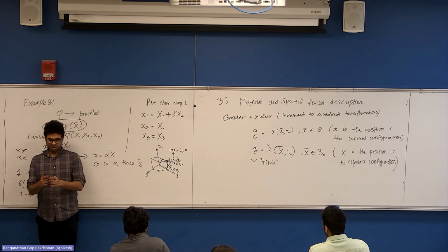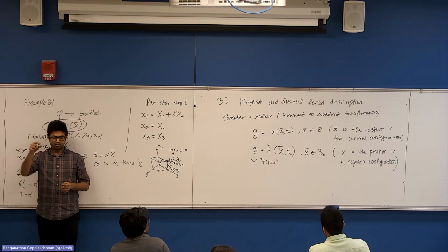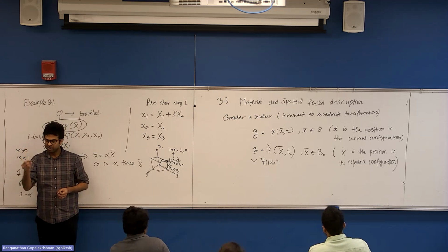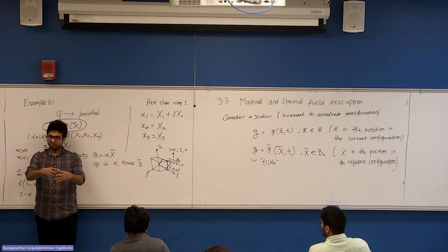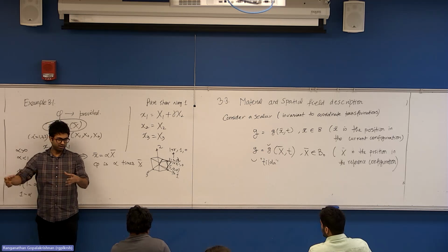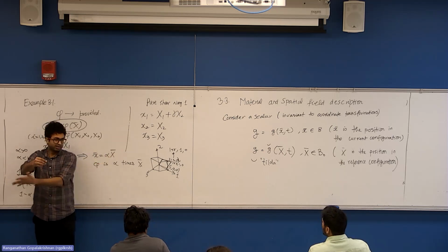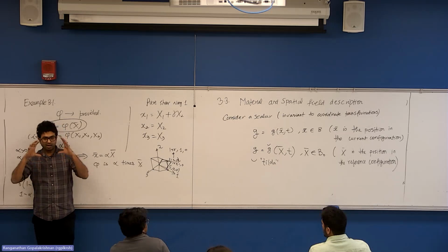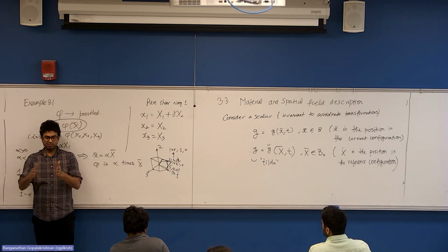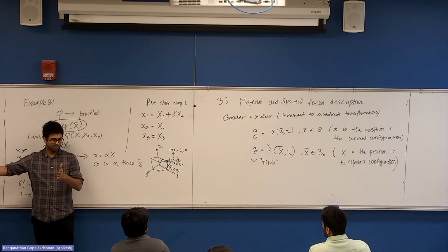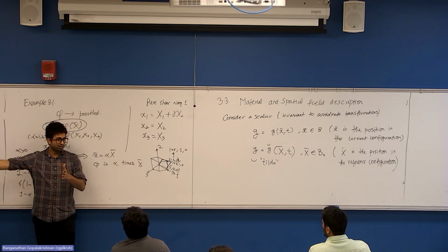Suppose I have a tiny dropper and I have a dye in the dropper. I take it to a point in my water tunnel or wind tunnel and I drop that dye so that the fluid will carry it. And then I take a video. I see a time lapse of the dye getting dispersed in the fluid. So the dye basically follows the fluid molecules. Wherever the dye goes, you know that the fluid molecules are going there.